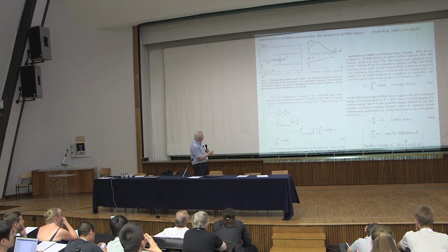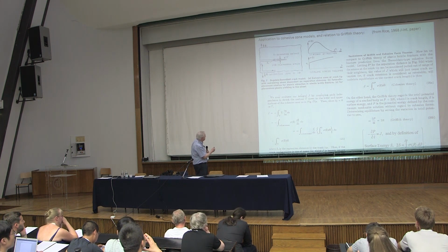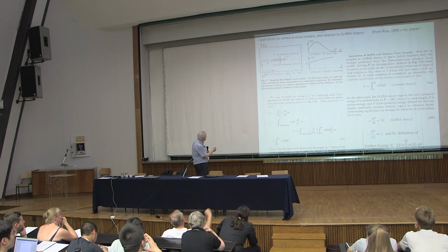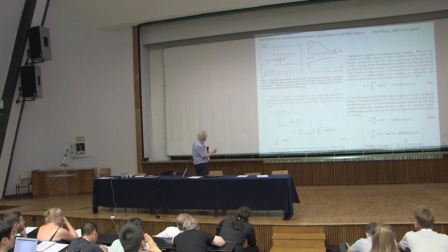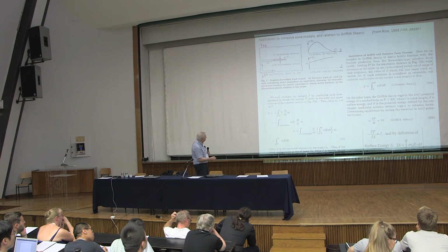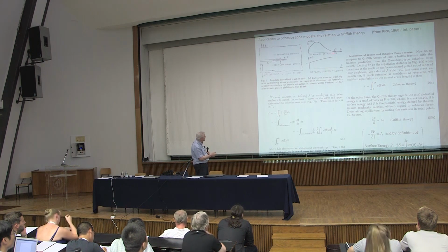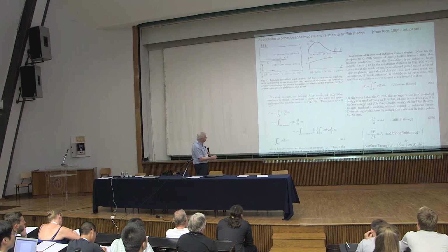But equally, you can take the same model and reinterpret it at a vastly smaller size scale, at a near atomic scale, as a kind of description of fracture as you slowly pull atoms out of range of one another, representing that in terms of a relation between a force per unit area and amount of separation. And it was then possible to show that J corresponded to the area under the stress versus separation distance curve up to the amount of separation that prevails at the crack tip.